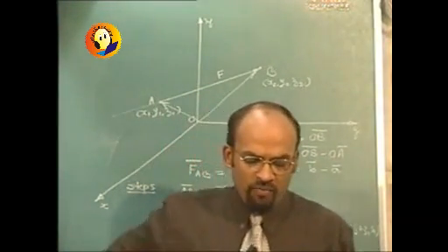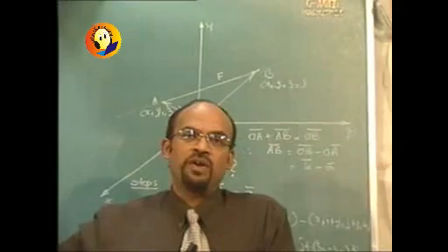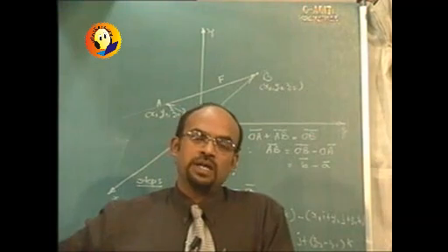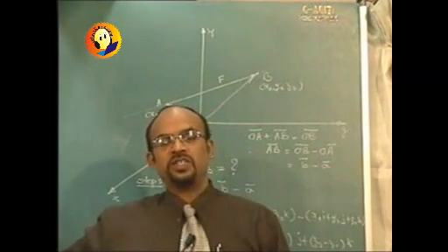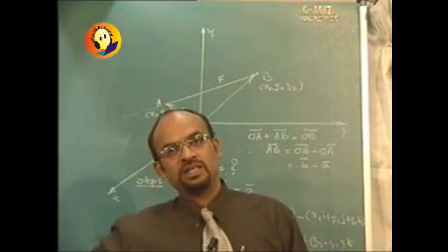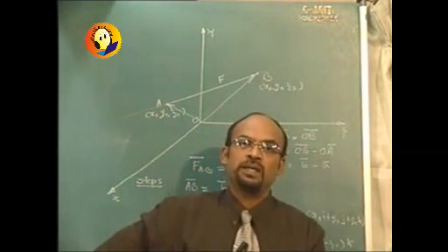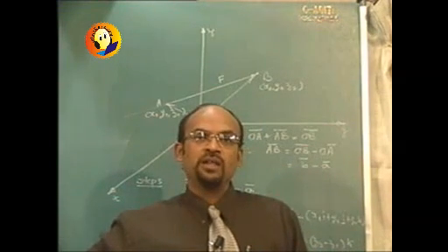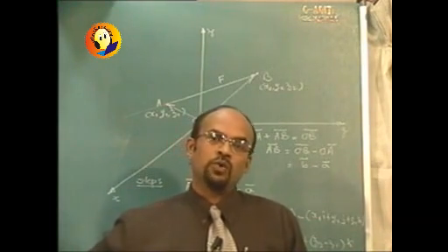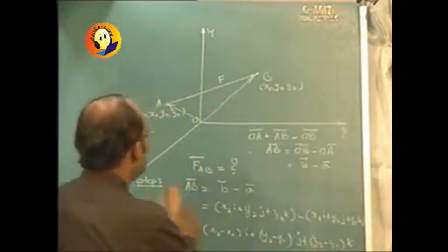So when we think of problems in 3D, we will first go for finding the coordinates of different points in the given figure, and then locate the starting point and ending point of every direction along which a force is acting. Once the directions are determined, individual vectors are found, and from those vectors we find the unit vectors. We multiply by the magnitude and get the vectors in the 3D vector form. Those forces will be obtained in the vector notation form, and then we will apply our standard rules of equilibrium. Let us consider a problem,